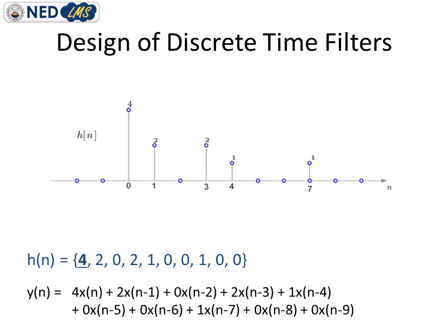However, we can follow the same procedure. Obviously, we can define the desired frequency response of an IIR filter and then take the inverse Fourier transform of that response to find out the filter's time domain impulse response. But unfortunately, there is no direct method for computation of its coefficients, that are AK and BK, from the impulse response. So the technique we applied in designing of FIR filters cannot be used to design the IIR filter.